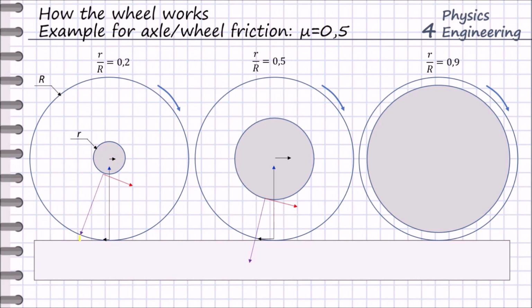The reaction force has almost the same length and the friction force almost the same length. Nevertheless, if you make projections of all these forces and calculate the torques, we will see that the equilibrium condition will be met only when the stiction force and driving force have a very small value. This correlates to the expectation that a smaller shaft diameter gives us a smaller resistance to the motion.